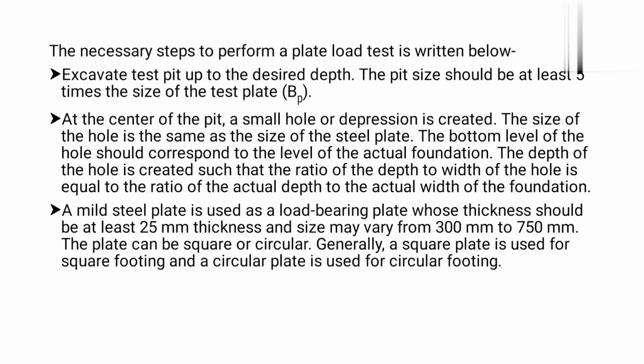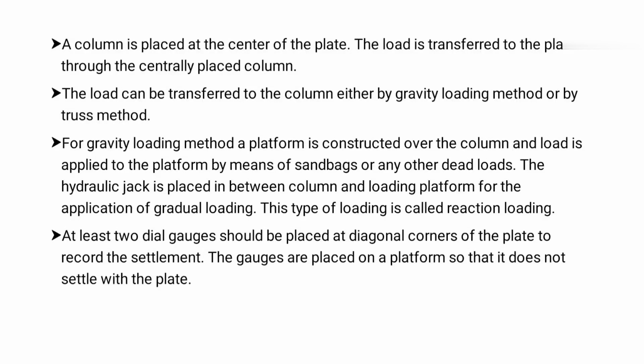Next, first we want to excavate a desirable pit. Then a test plate is placed at the center of the pit, and above that a column is placed, and load is transferred to the plate through a centrally placed column. Here the load can be transferred to the column either by the gravity load method or the reaction truss method. In the gravity load method, we make a platform constructed over the column, and load is applied by means of a sandbag or any other dead load, and a hydraulic jack is placed in between them to transfer the load gradually. For the reaction truss, we are constructing a truss above the rigid plate.